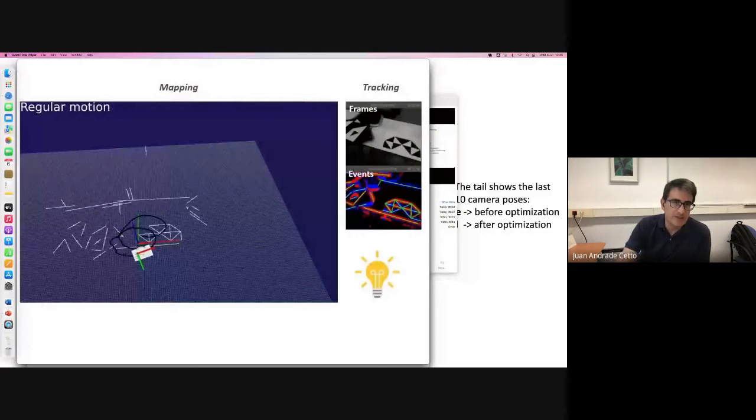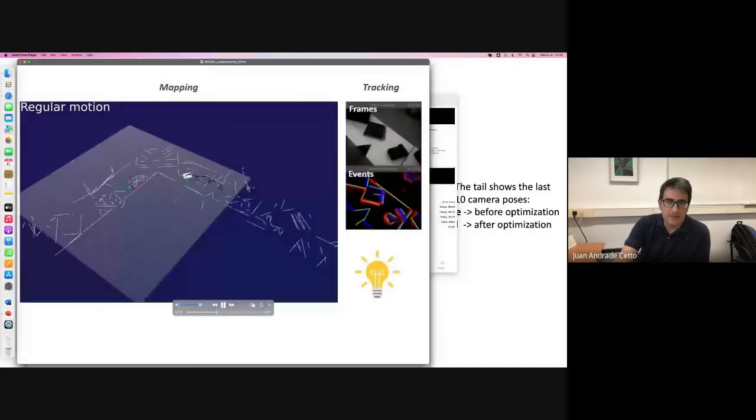So in here, you can see the tracking module leaving a trail in black, and you will see the results of the whole mapping part, and you can see that the structure is accurately estimated. You could turn off the lights in the laboratory, and the mapping and tracking system, because of the properties of this type of cameras, will continue as before. So in this case, this is the SLAM module working in a scenario of about 20 square meters, more or less.